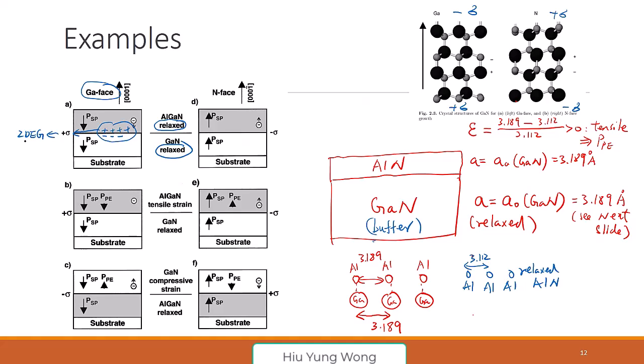Let's say it introduces one electron, okay? Here, I give you another thing. Now the aluminum gallium nitride is under tensile stress. Just trust me, since they match, it's tensile stress, like what I discussed here. They pull away. You can use the equation and trust it. We don't have time to go through the physics. This tensile stress adds an additional piezoelectric polarization.